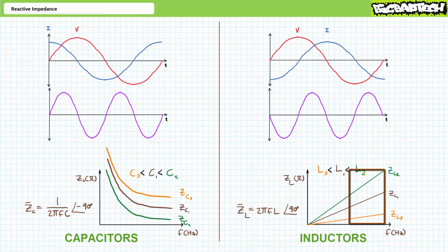Conversely, inductors present high impedance and draw low current at high frequencies. This is a reflection of how frequency influences the expansion or collapsing of the magnetic field. Slower frequencies result in a slower changing magnetic field, thus lesser oppositional voltage and more current. Conversely, more rapid frequencies result in a more rapidly changing magnetic field and greater oppositional voltage and less current.